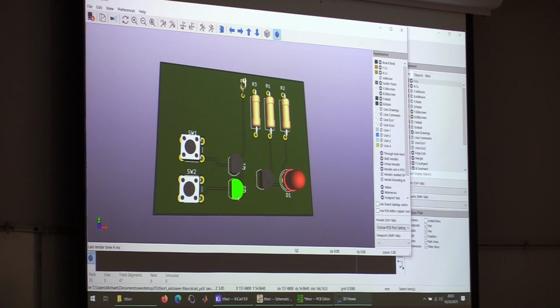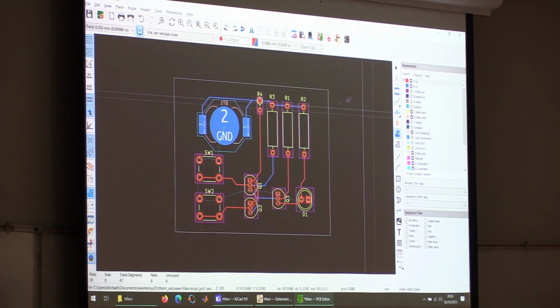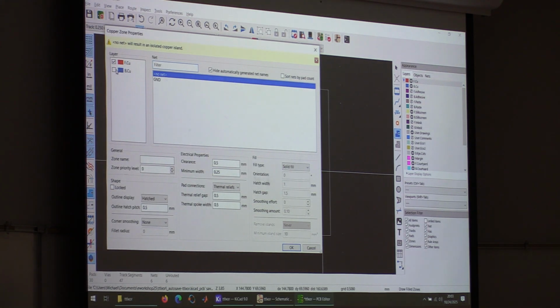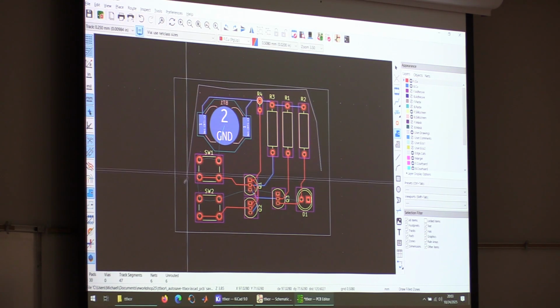Yeah. If we have a really weird shape, what should we do? Should we try to draw the complete outline? Are you talking about routing the trace, or are you talking about the fill zone? Yeah, the fill zone. You can totally do that. Say for instance, I have an awkwardly shaped board. What I can do is, say I want to have a circle fill layer on the front. I'll do that. I'll hit OK, and I will just start drawing as I see fit.